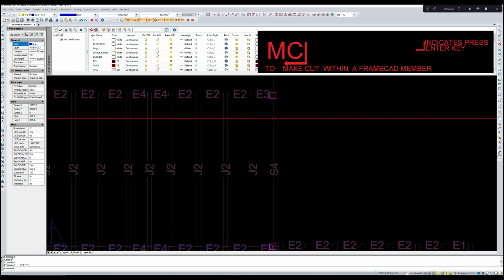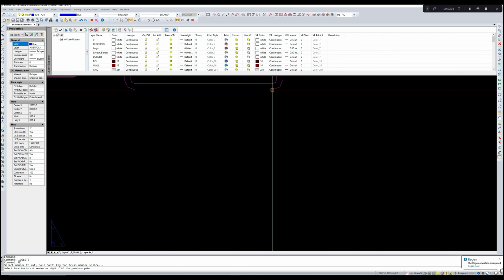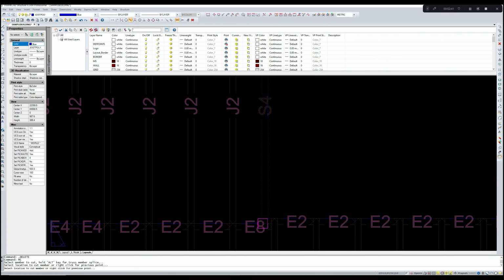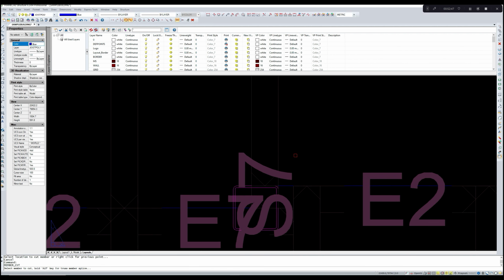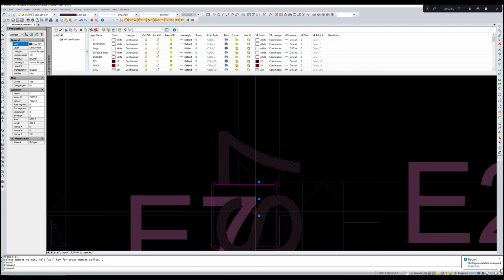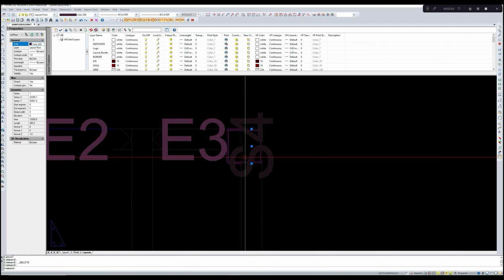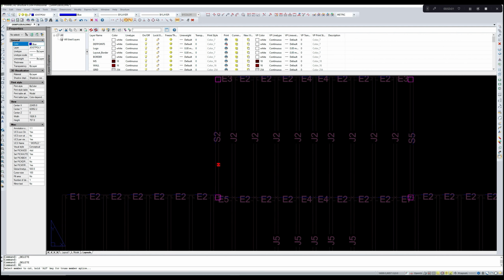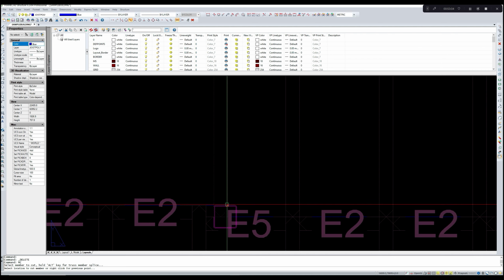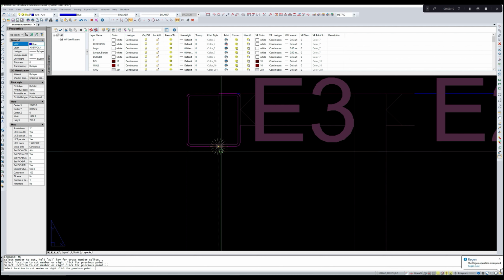Now select this member, MC again, member cut, select the side, select here, select here, enter. So delete the extra portion. Again MC, enter. This point, this point, enter.